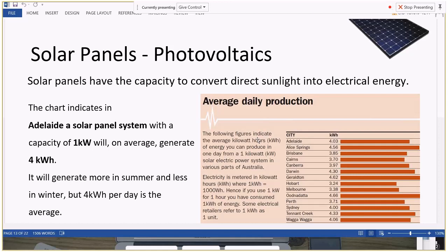let's say we bought a block of land in the hills, something like that, and we had to run power for 200 metres. It gets very expensive to run power that longer distance, because it's not just that we have to go, all right, this is how much it cost me to run power for 10 metres and then multiply that by 20. When you supply power, let's say at 240 volts, and you run that for a longer distance through a small cable, you get voltage drop over that small cable.